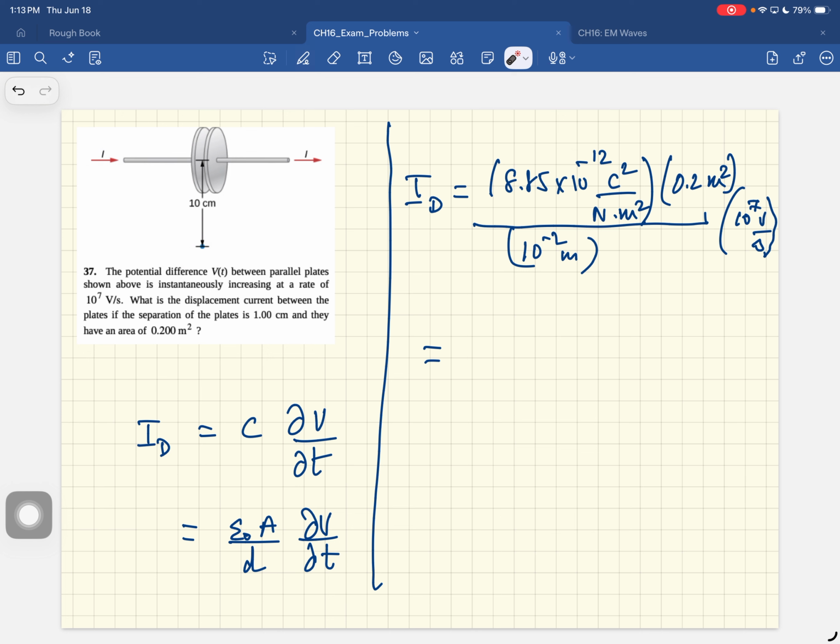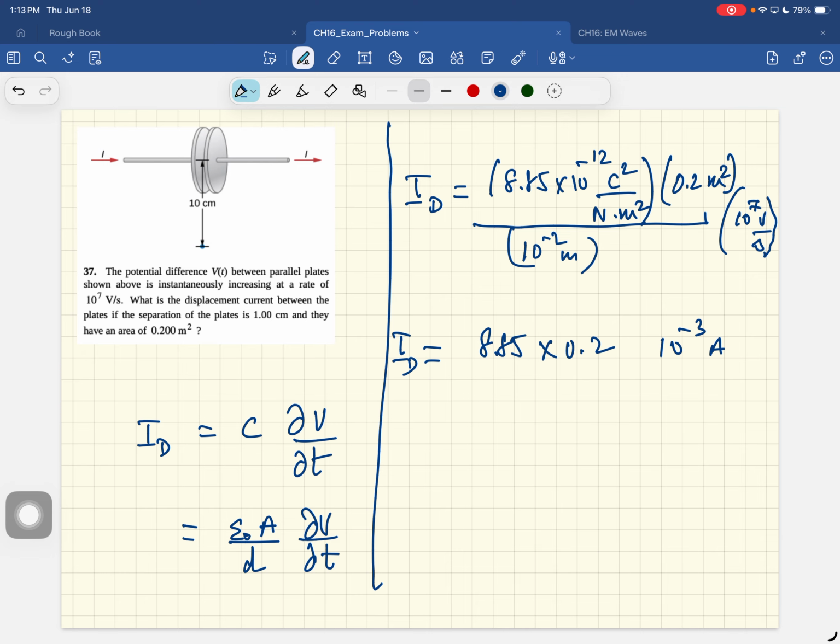All right, so if you're receiving an electromagnetic wave from Orlando, Orlando is in that direction, the electric field is coming like this, the magnetic field is coming like that. So if you want to catch the electromagnetic wave, if you're using rabbit ears, a dipole antenna, you want the dipole antenna to be like that.